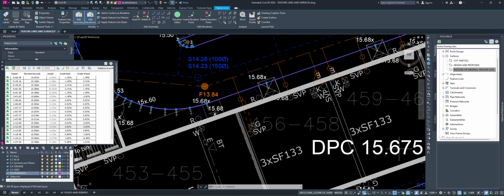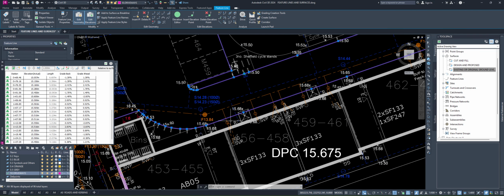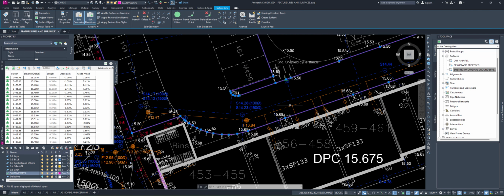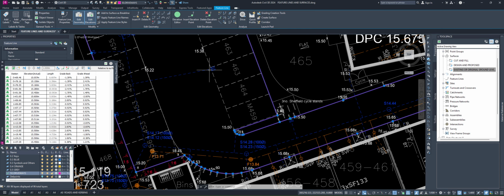We're slightly lower, by 25 mil, in here. There isn't going to be water accumulating on this point. The crossflow is going to work back towards that gully in this instance, and the long flow is going to keep everything else back towards that gully, and again back to here and back to here.